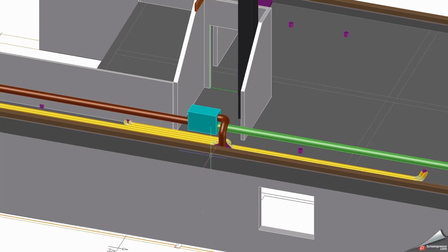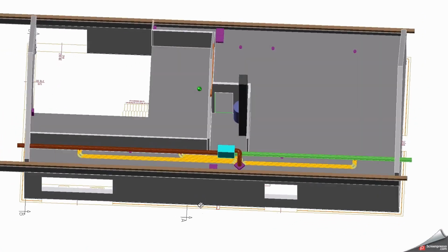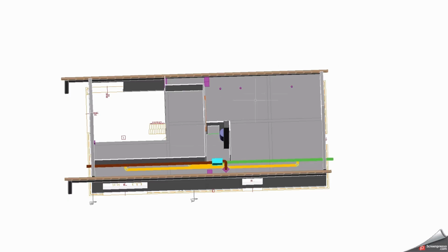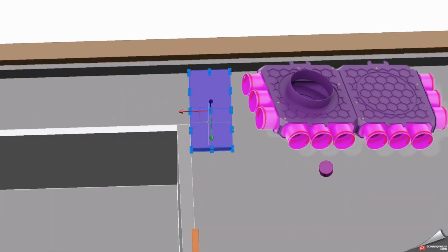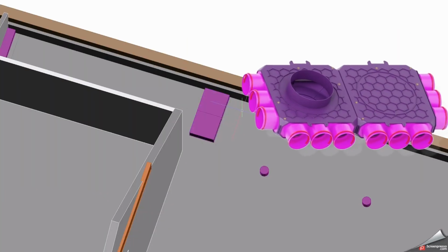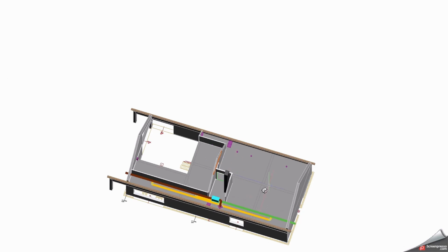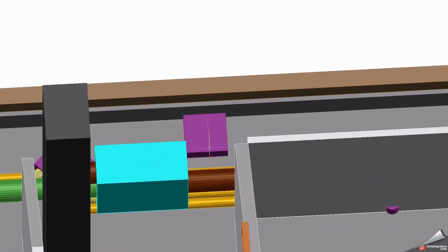Now we're getting to the more complicated part, the air supply distribution boxes. The majority of the rooms that require an air supply system are primarily situated in the western section of the house, and there we will install a double plenum box equipped with 12 separate inlets for the ducts. However, we also need to extend the ductwork to the small bedroom located on the eastern side, as well as to the pantry and the living room, which features a high ceiling.